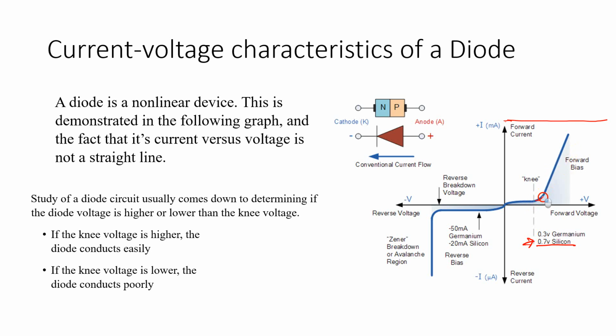And you're seeing here that it now starts to conduct like this, where, with an increase in voltage, more current is increasing, where the resistance is going to be constant for a period of time, right? So this portion just now tells us that the diode is now conducting and it's now in forward bias. Follow me?